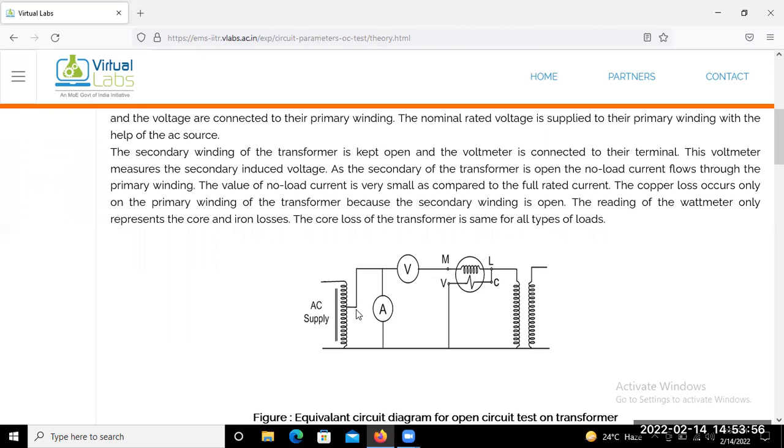Okay. So movement of this auto transformer variac just changes the position. Corresponding to that, you may find the connection of voltmeter and ammeter reversed here. So the voltmeter is connected here instead of here. And the ammeter is connected here instead of in parallel. So don't get confused by this diagram about the connection of ammeter and voltmeter. The voltmeter is connected across, in parallel, and the ammeter is always connected in series with it.